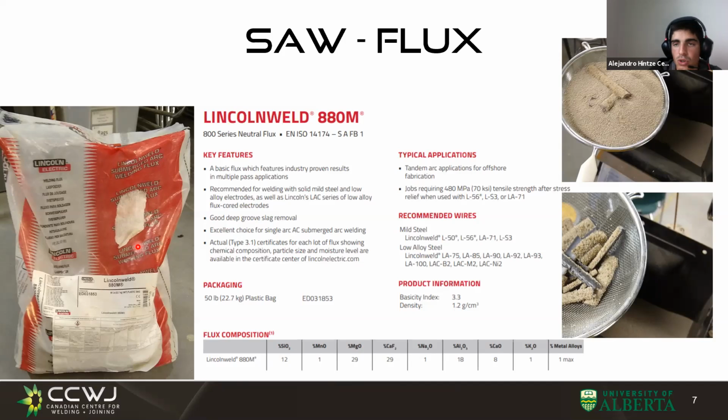And also I want to show you this because these fluxes come in this big bag and they're pretty expensive. And you might ask yourself, okay, I made a run, and then all the extra flux that we have, that you'll see in action, where does it go? You can reuse it, and this is how we reuse it in the lab. We just take the slag that comes off and all the powders, put them in a colander, and take off all the powder that still has some life into the hopper, so it can be reused again.